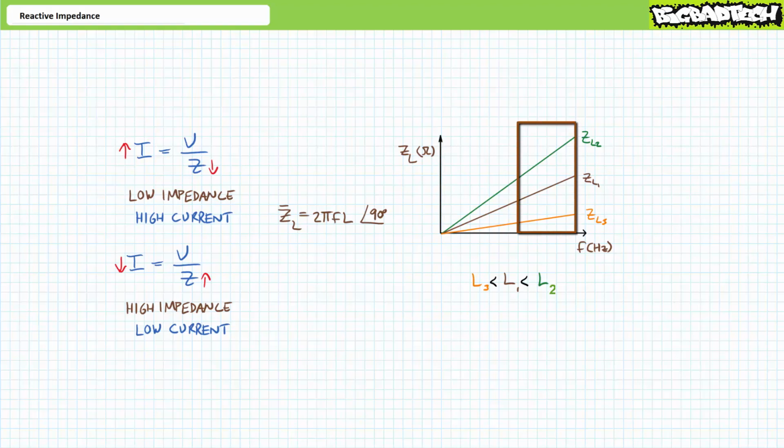Conversely, at high frequencies, quickly oscillating waveforms make the magnetic field rapidly expand and contract, resulting in high oppositional voltage spikes, keeping current at a smaller, more manageable level, i.e. current is lower at high frequencies, synonymous with high impedance elements. If you think about it, inductors in high-frequency systems are always in the early stages of a storage or release, synonymous with larger bursts of oppositional voltage.